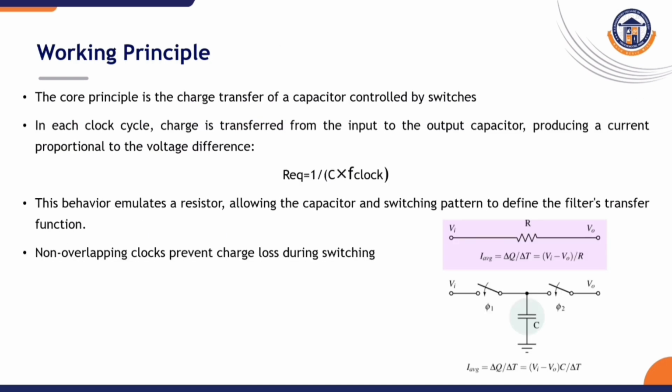So, the working principle. The core principle is the charge transfer of a capacitor controlled by the switches. The basic idea is the charge transfer. A capacitor is charged during one clock phase. It transfers the charge during the next phase. This repeated charge transfer creates a current.